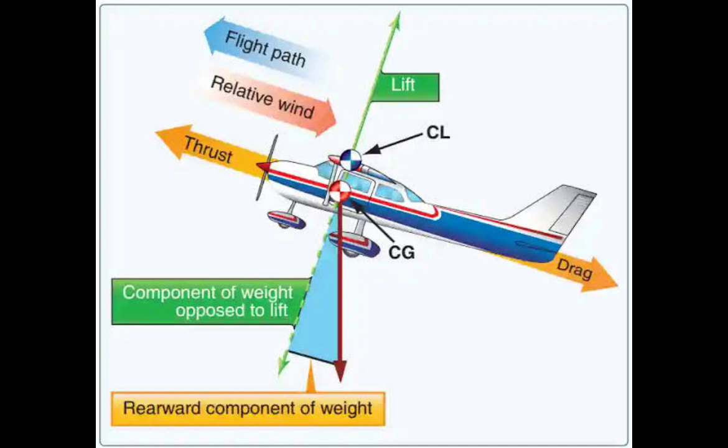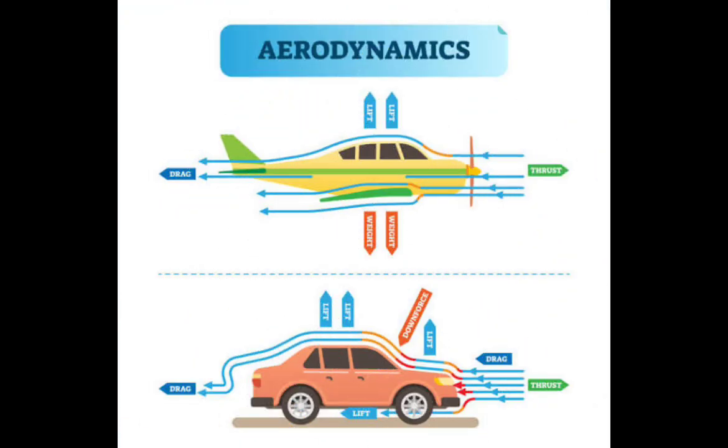Finally, for the landing, the pilot reduces thrust, which in turn reduces speed and lift. To compensate, the flaps on the wings are extended. This increases both lift at lower speed and also increases the drag, helping the plane to slow down safely for landing.